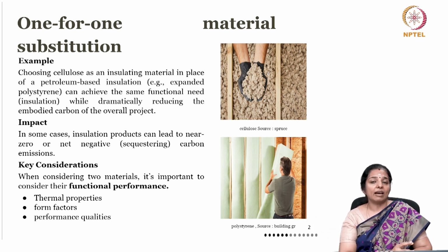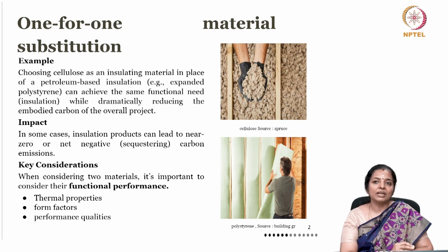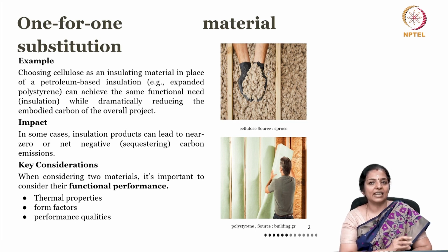Whereas, if you have carpet tiles, then it can result in 1 to 5% installation waste as against 10 to 20% installation waste in the broadloom carpets. And the useful life of the floor can also be extended with selective tile by tile replacement for damaged sections. So, specify carpet tile to minimize waste and waste associated emissions, such as landfill emissions and emissions associated with the production of a new or replacement material.